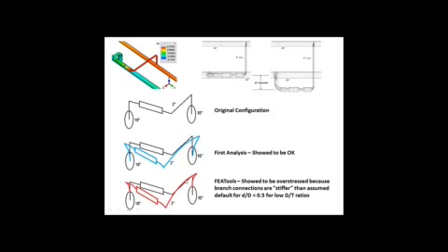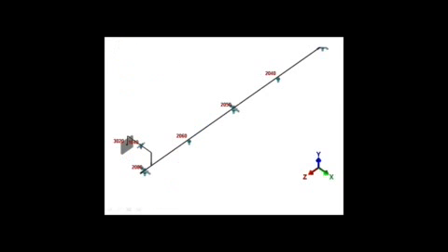When we ran FEA Tools, it says that's not what really happens. FEA Tools builds what we see with the red piping system, so it puts rigid elements from the center line out to the surface for everything, because that's the way the systems really behave structurally. So in this case we put a lot more bending back on the elbows, and the elbows were overstressed, and we need a little bit more flexibility. FEA Tools showed us where we weren't conservative with these small branch connections.